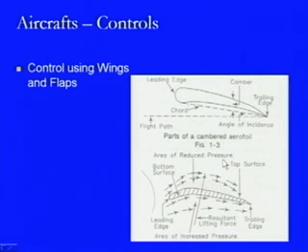This is another diagram which is trying to show the same sort of lift condition. Here this is an aerodynamic profile of the wing, and we can see this is the overall chord. If we join from this point to this point, that is the chord, and this is the type of camber being provided. This is the front side, this is the back side. So, this is the trailing edge and this is the leading edge, and when it moves, the air will be coming from this direction.